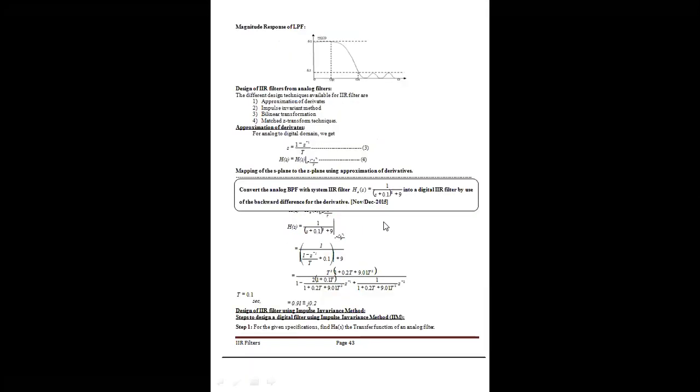Similarly, substitute the value for k is equivalent to 2 and we'll be getting the value of S2 over here. So when you are finding the denominator of H of S, this is the expression of the same value. So S plus 643.465 plus j 1553 by 4, the whole square. So when you are substituting S is equivalent to 0, so what will happen? H of S is equivalent to this divided by root of 1 plus epsilon squared, and we know the value of epsilon is equivalent to 1. By that we are able to find the value of the transfer function H of S. So this is the way to design our Chebyshev filter.